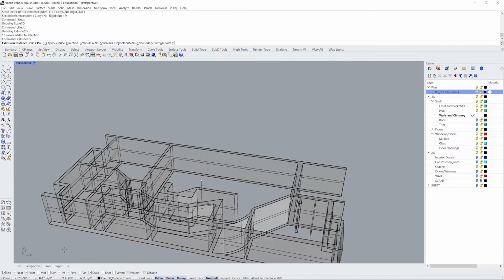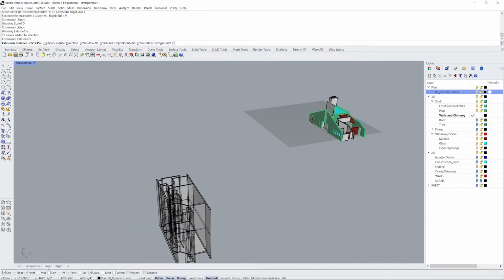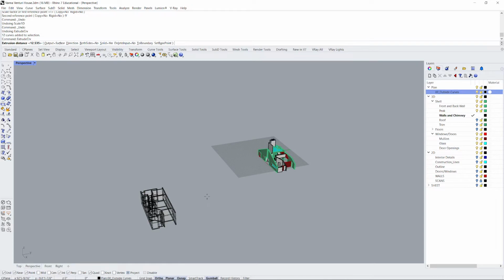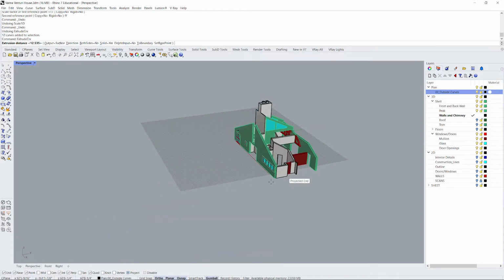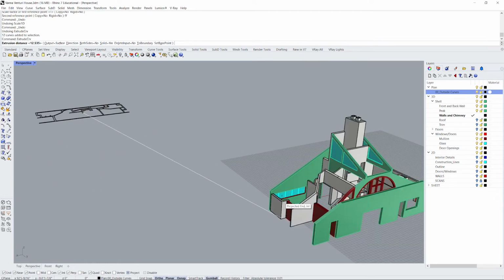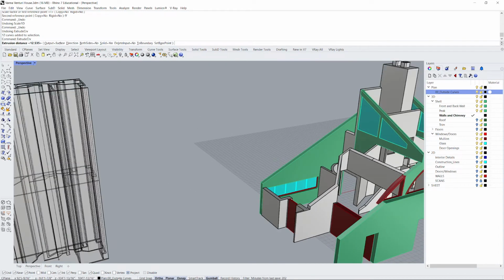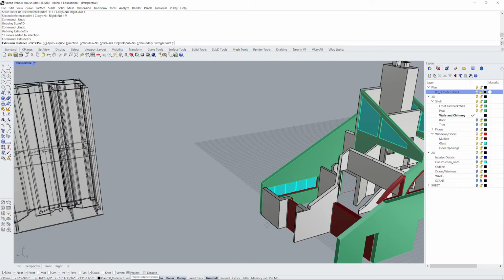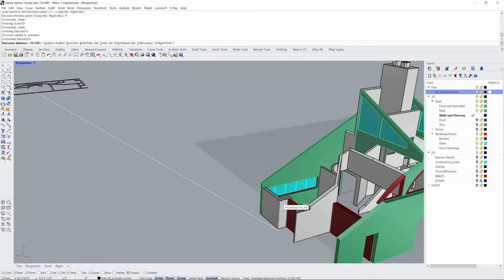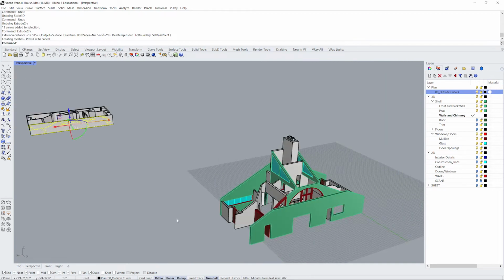If you're trying to object snap to something that's in front view, and then you have the project checkbox in the object snaps selected, that's always going to be kind of difficult to work with, because if you are trying to select this upper point, it won't let you because the project button is selected. So it's projecting to the C plane even though it's object snapping to something up in the air. So you just need to turn that off, and then you can click.